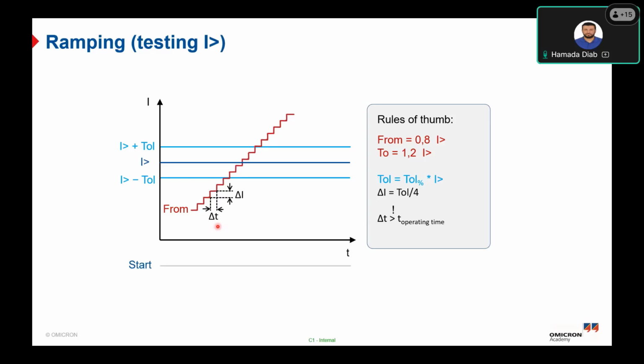Okay. So now we will see how to assess the result. We will take the start contact, which is the pickup contact from the relay binary output to the CMC binary input, and we will define the trigger condition from 0 to 1, which means the start contact will be normally open in the beginning, and it will change to closed after detecting the pickup value.